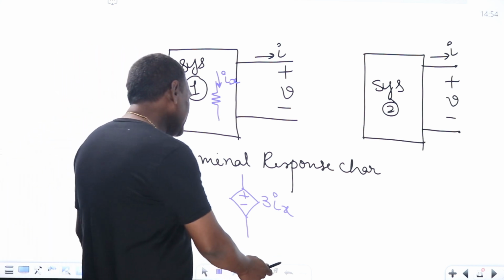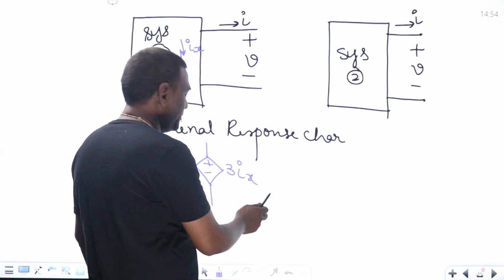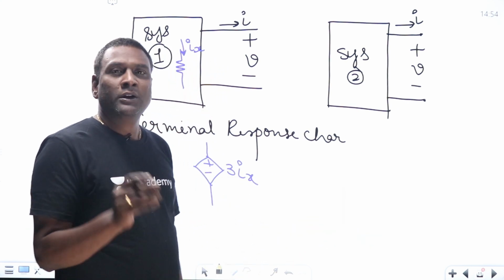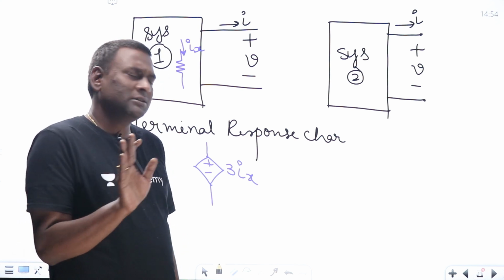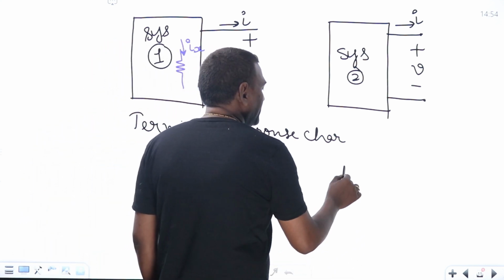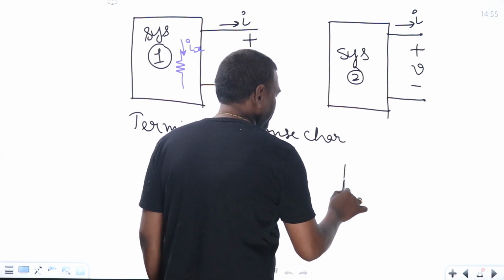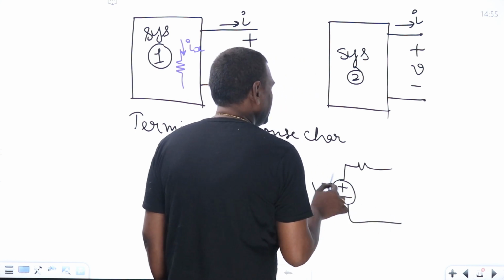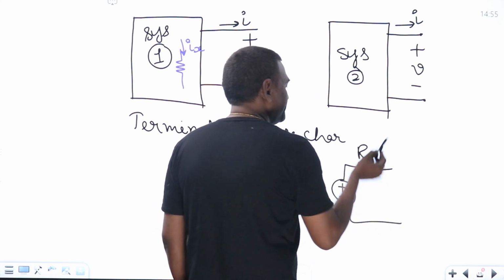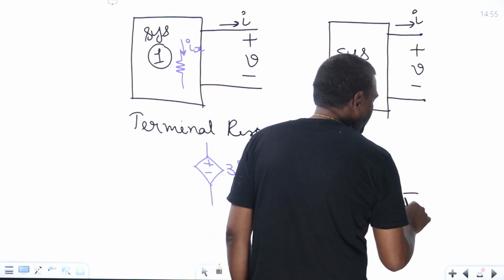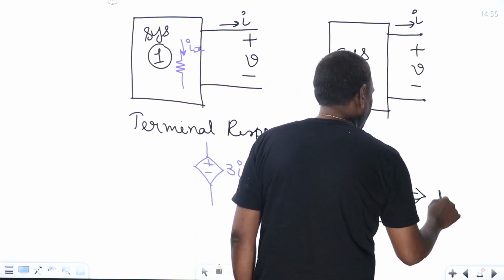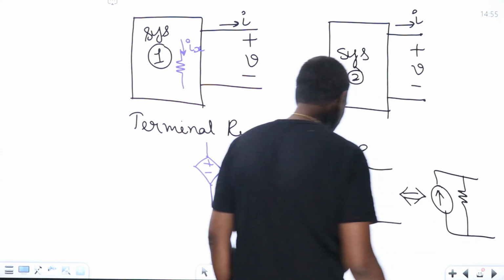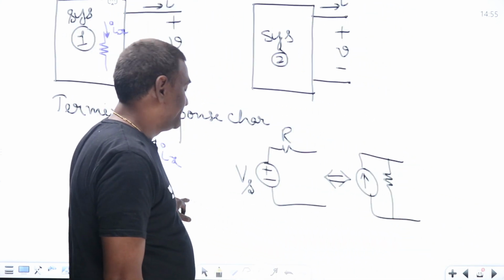And the next thing is, if they ask you anything internal to the system. I already know how to transform sources. Let me take an example: one voltage source in series with a resistor, this is Vs, this is R. I can convert this into an equivalent current source, because boundaries are always very, very important.